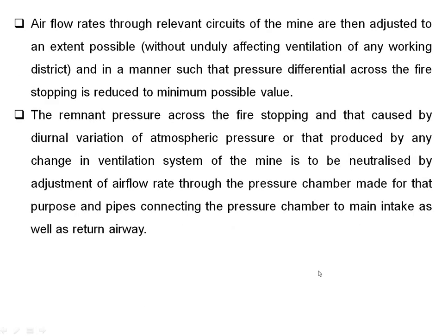The airflow rates through the relevant circuits of a mine are adjusted to the extent possible, so the pressure differential across the fire stopping is reduced to the minimum possible. The relevant circuits of the mine are adjusted to the extent possible without unduly affecting the ventilation of any district. But that is the most important thing, as well as the remnant pressure.